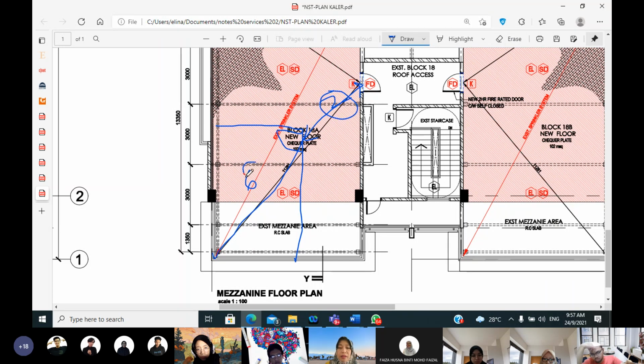The distance is so that the firemen and occupants of the building can evacuate immediately, because when we design this fire door, it is rated only 1 hour, meaning that we have to escape within that time. If more than that, the door and the partition will be destroyed. That is why we have to indicate in detail why a 1 hour or 2 hour fire rated door.